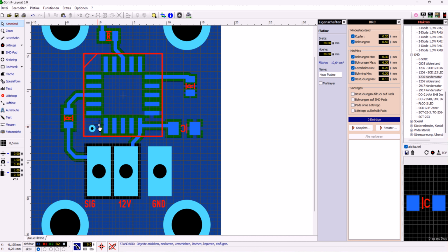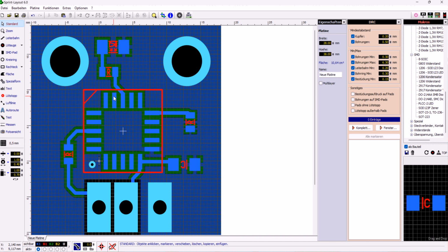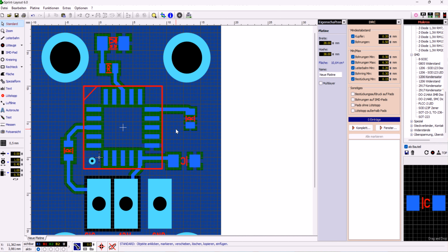Yes, I think that's mostly it for that video. Yeah, that's about it. So, ground planes. As I said, they're used for shielding and for saving traces on your design. To make it like that, it's much easier. You have much more space for other components, because you don't have to sneak in a ground trace like that around here. So you could put much more components on your layout.